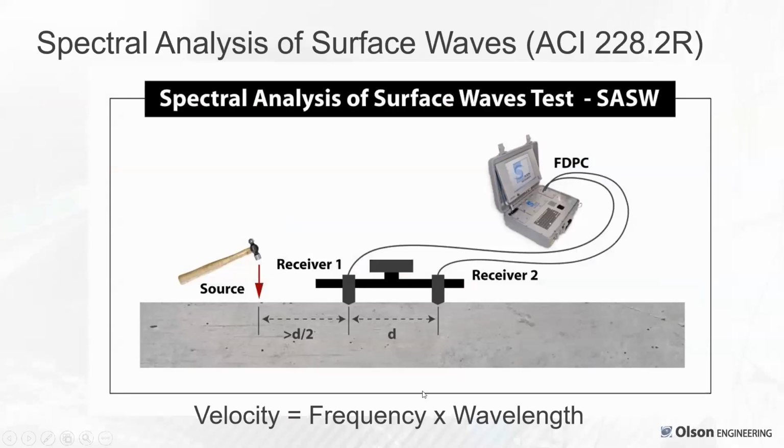But what he had come up with was the idea of looking at surface waves with more sophisticated measurement and modeling to, from the surface, determine the variation of shear wave velocity versus depth for soil sites. It's been expanded to pavements and structures, and also it's evolved into the multi-channel analyses of surface wave methods.